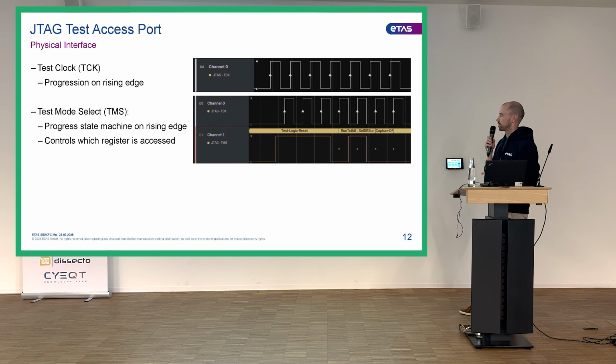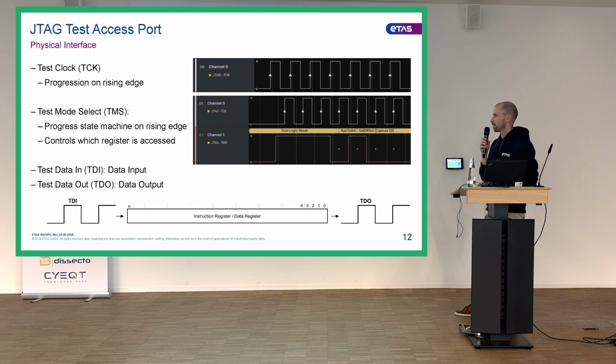And we can see here, it starts out in this reset state, and then it stays in this reset state as long as TMS is 1. And then at some point, TMS transitions to 0, and then we can see on the rising edge, it changes to idle, and then it goes through this column of states to update the data register.